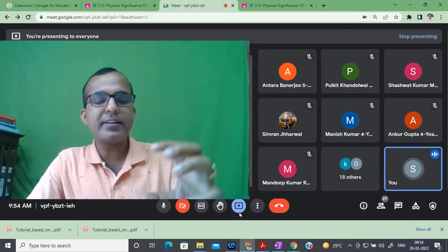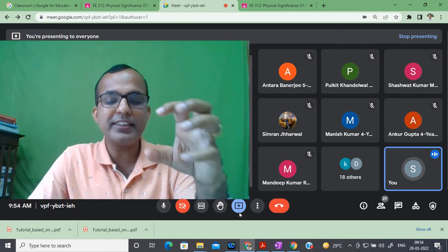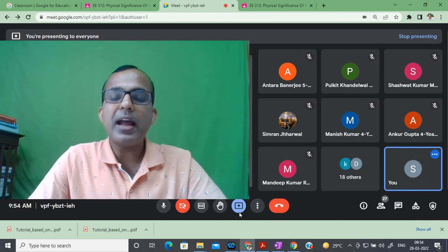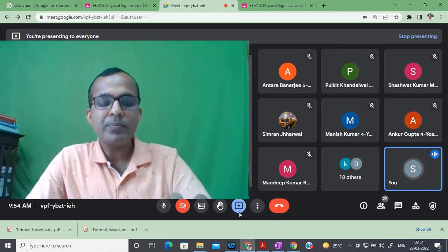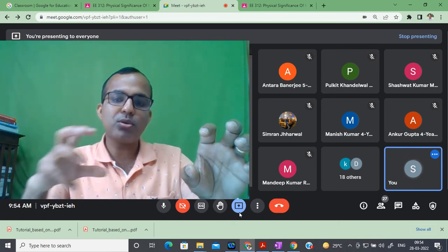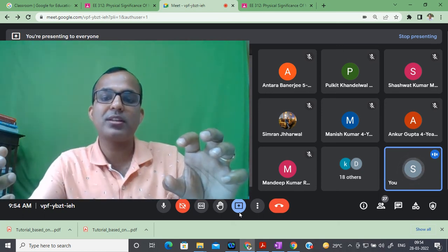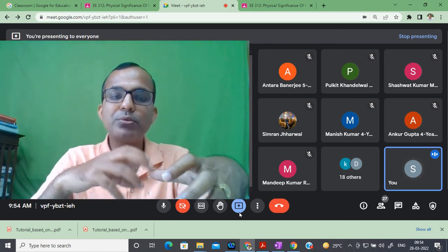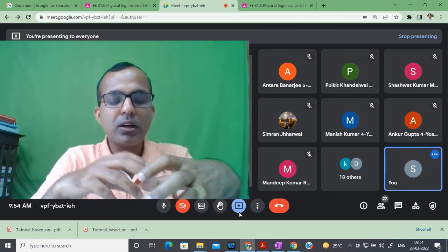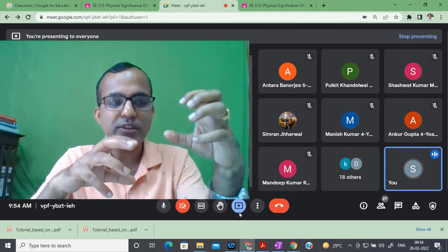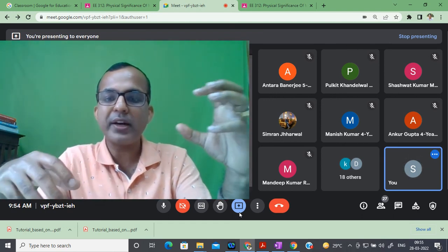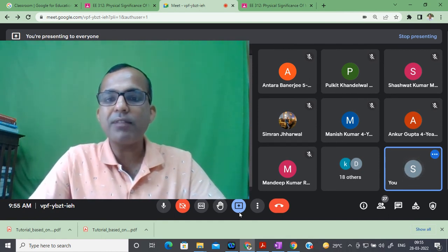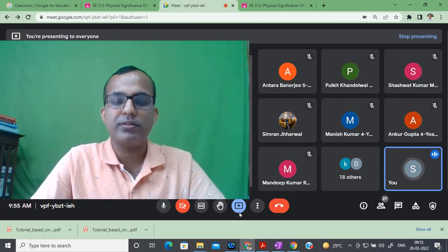Try to write the differential equation, or Euler-Lagrange equation, for each and every subsystem. Identify the force along the first subsystem, the force along the second subsystem, and the force along the third subsystem, and equate them individually. After that, check what kinetic energy is associated with each system and add all of it. Do the same for the potential energy, and then solve the partial differential equation, and after solving that you are able to get the second order differential equation.